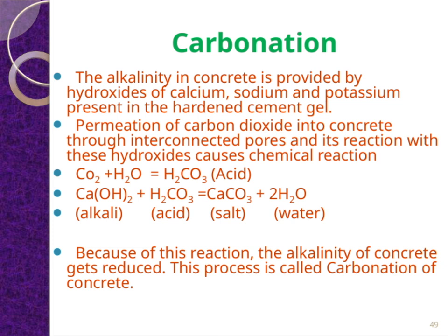The carbon dioxide combines with water to create H2CO3, or carbonic acid, which then reacts with calcium hydroxide, Ca(OH)2, in the concrete. This reaction produces calcium carbonate, CaCO3, and water. What's key here is that this process reduces the alkalinity of the concrete, and this phenomenon is known as carbonation of concrete.